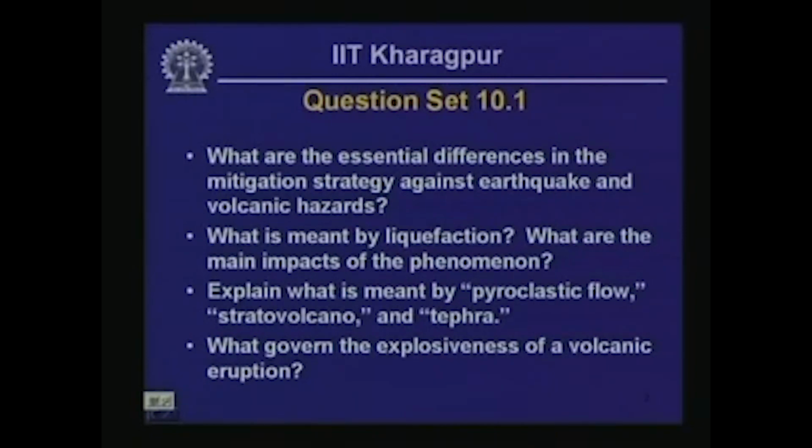The second question that I asked was, what is meant by liquefaction and what are the main impacts of the phenomenon? Now, liquefaction is primarily a phenomenon associated with elevation of pore water pressure within the matrix of relatively coarse-grained soils, which derive most of their strength from frictional interaction between different individual particles that compose the medium.